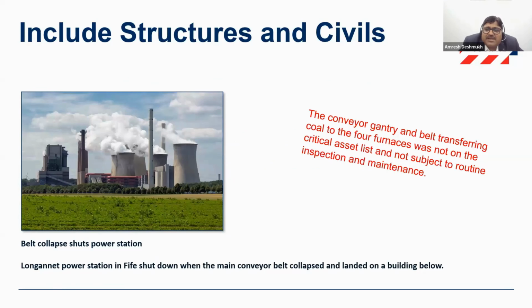Now, one more thing which people generally miss is they do not consider the structures, the pipelines, the pipe racks, the pipe bridges, or the structural facilities in the plant which are acting as supports to the hazardous equipment that is put to use. It's necessary that we also do structural audits for the entire facility, and we assure ourselves that the structural strength is sufficient for you to use that facility at least till the next operational cycle.